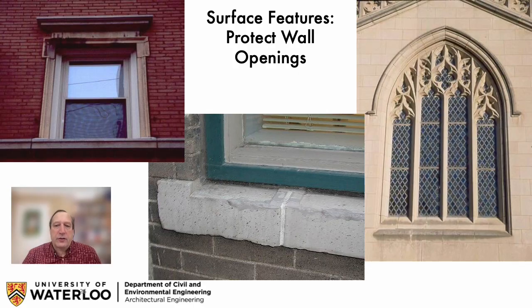It's somewhat ironic to me that many of these details exist in buildings that have really thick walls made out of highly durable and moisture-tolerant materials like masonry, and then we don't use them when we build buildings that are made out of light-gauge steel stud or fast-growing plantation wood framing.